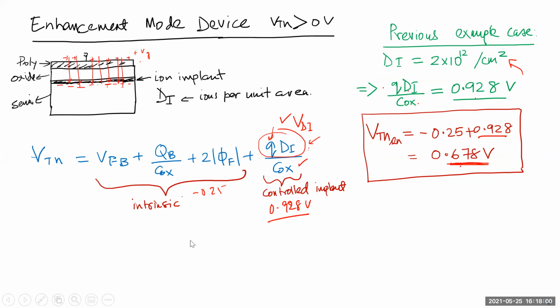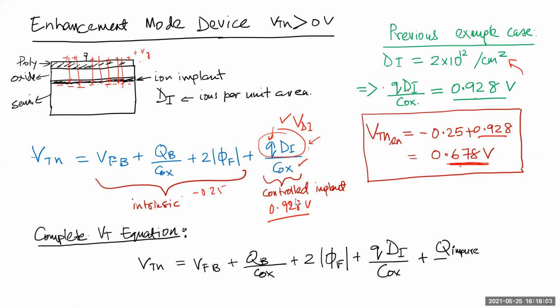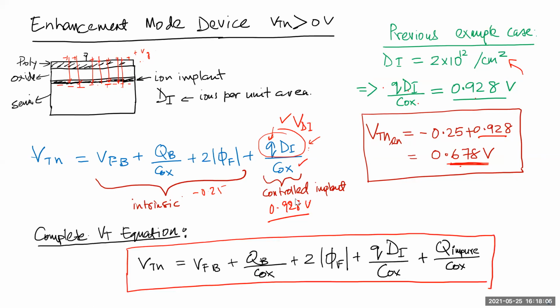All right, so as I said, I will explain this. There was another term I forgot to mention, and this term is the impurity inside the oxide. What happens is when you do the oxide growth, because you are doing all this diffusion and metallization, there is always impurity which diffuses into the oxide. For example, if you're doing silicon dioxide and you have some ion implantation, some of that ion will actually diffuse into it.